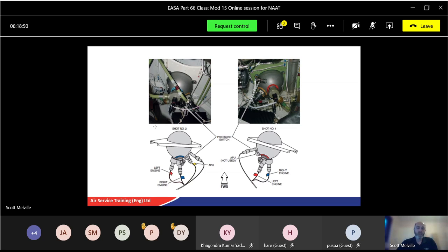Accidental discharge may cause injury. You've got that very cold discharge coming out, and you get instant freezing of the skin, which can cause a lot of damage. Obviously you're in the area where it's gone off, so you can inhale that, which can cause problems as well. So before you fit an extinguisher, make sure you have no power available: circuit breakers, no volts check, and everything in the off position.